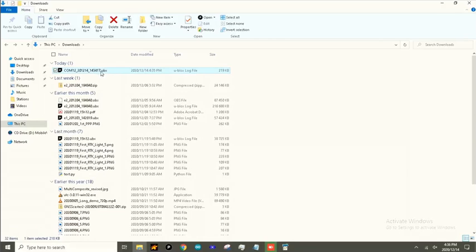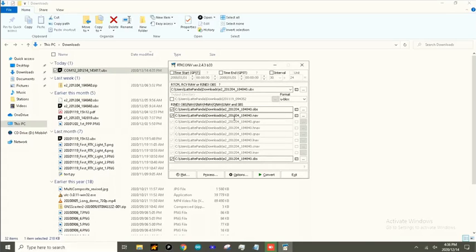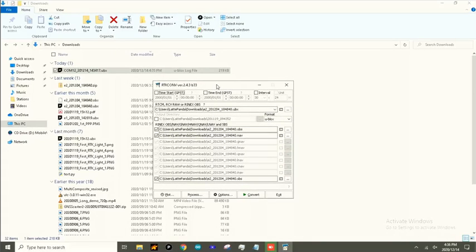So we're going to use a third-party program called RTKLIB. It's a collection of software utilities specifically catered toward GNSS systems and applications. So from RTKLIB you'll find in the applicable folder there's a utility called RTKCONV, which I believe is short for RTK Convert. This will take this u-blox file format and provide us with observation files, and it is this file that will be used in the last step of the post-processing pipeline.